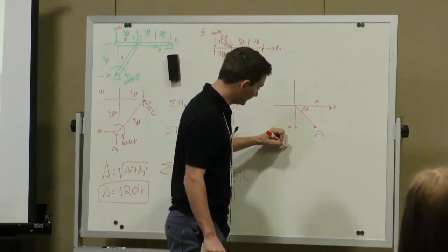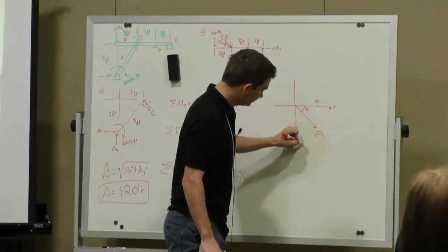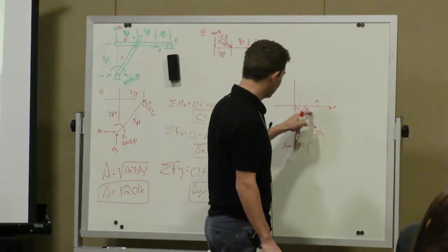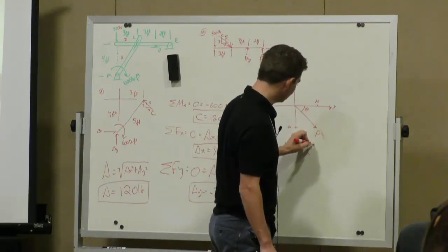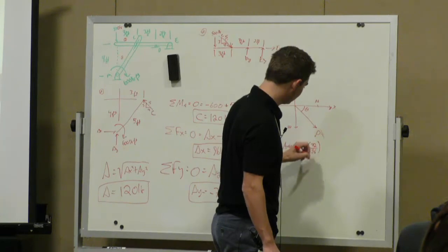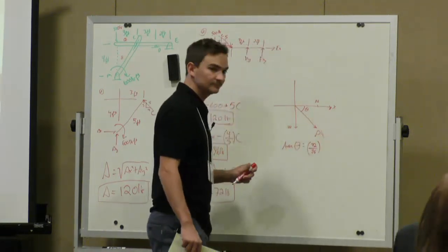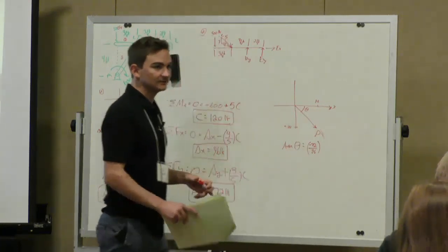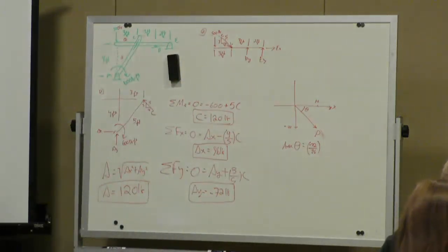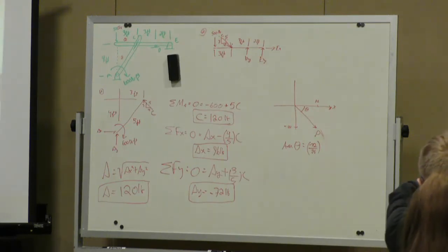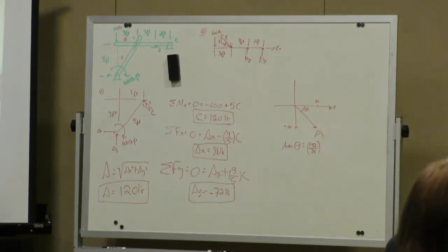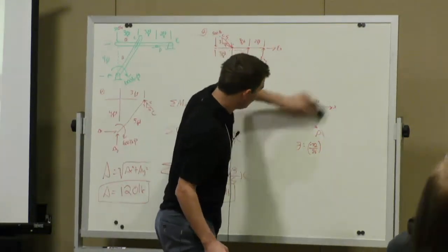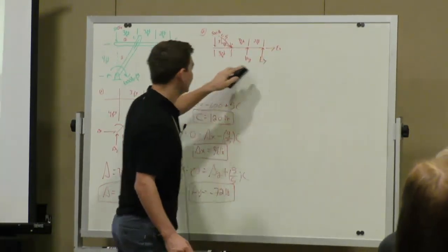Yeah, so tangent theta is equal to your opposite, which is your 72, over adjacent. Does everyone see that? Of course, this is negative. And then you would just do inverse tangent. So that's not too critical in this problem, but it's good to know how to solve for it. All right. So now we have our support reactions at A, we still need D and E.